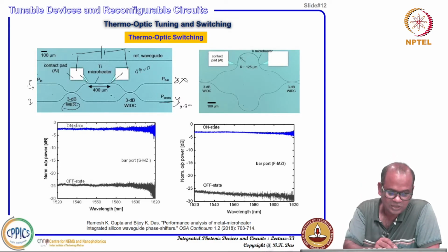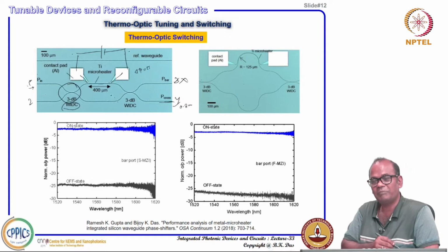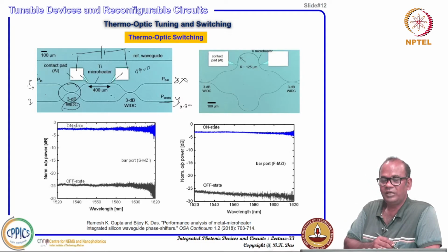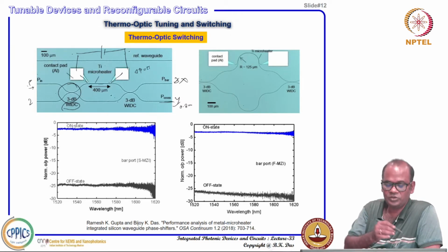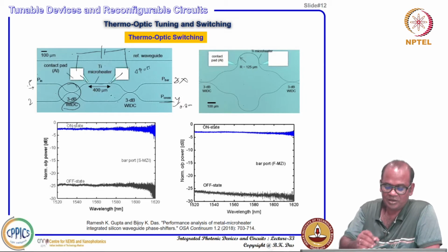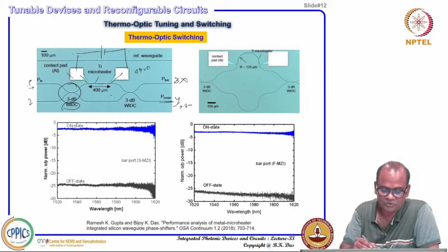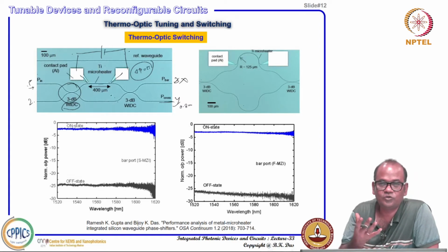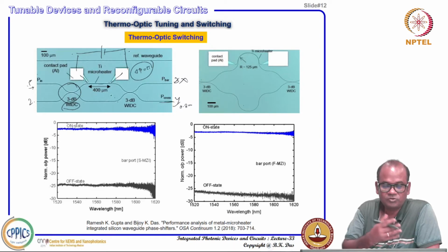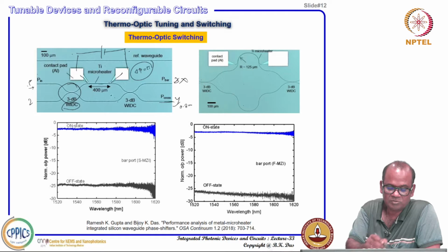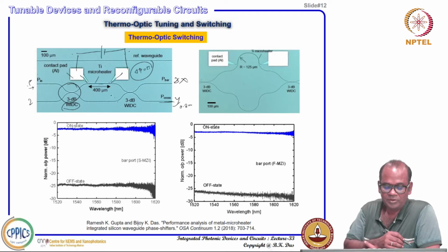Okay. And since these directional couplers are designed to be wavelength independent, any wavelength from 1520 to 1620 nanometers has been tested, and for all wavelengths you can switch the entire power by just giving a pi phase shift. This is the actual device fabricated in our lab, and this is the optical micrograph, a photograph of the Mach Zehnder interferometer. The microheater length is 400 micrometer here.